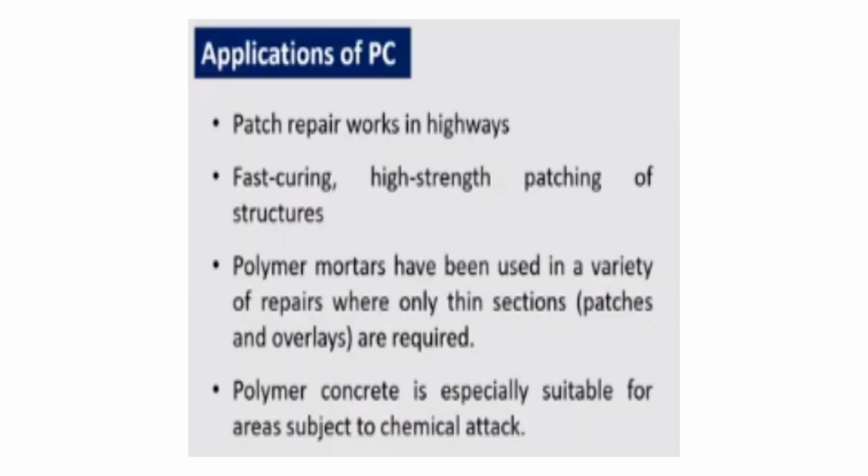Okay, so let us see what the applications of polymer concrete are. Basically they are used in patch repair works in highways. They can be used for fast curing, high strength patching of structures. The polymer mortars have been used in a variety of repairs where only thin sections, that is patches and overlays, are required. Polymer concrete is especially suitable for areas subjected to chemical attack. So these are some of the areas where polymer concrete can be used.